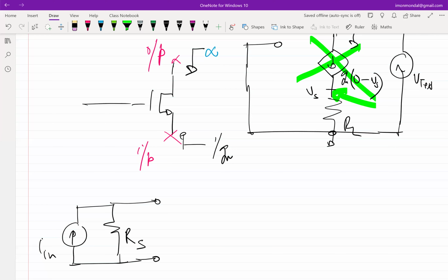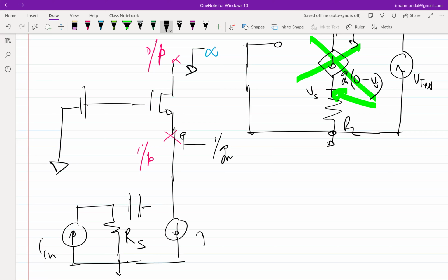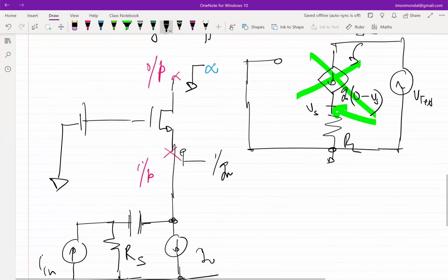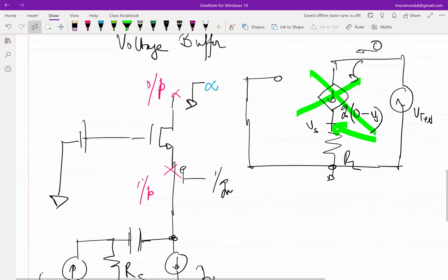At the gate side, what should I do? Constant voltage. Again, we know multiple ways of doing that, so I am not bothering. So on the source side, capacitor, and then yes. So I have a capacitor, but what I'm asking is, how should I bias this? We can bias it the same way we have been doing till now. I naught, and this couple goes here. And on the drain side,